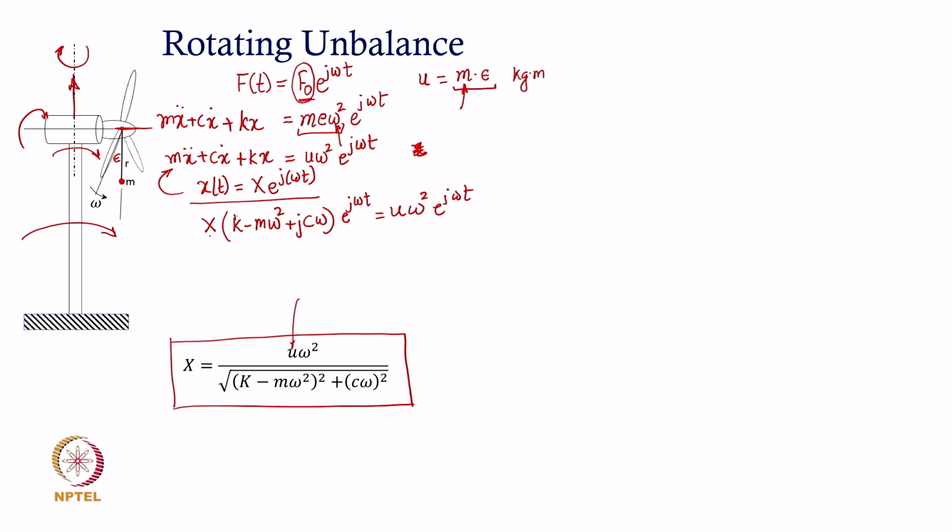Obviously, we are not accounting for the transient part of the total response, that we have discussed a number of times why it is typically neglected or ignored. So, steady state vibratory response amplitude capital X is given by this expression, and that is typically how the rotating unbalance excitation generates vibratory response capital X.